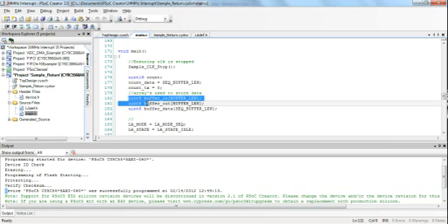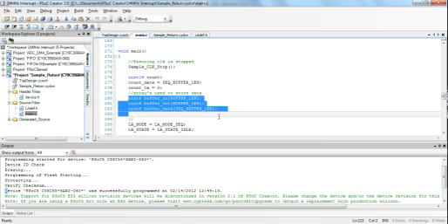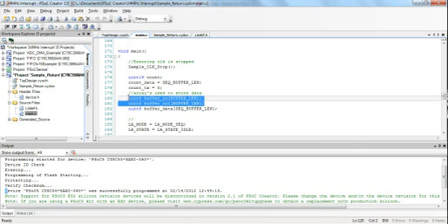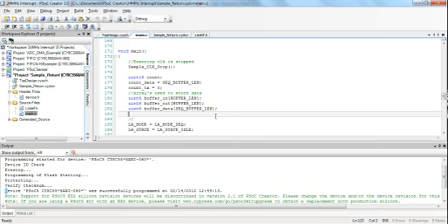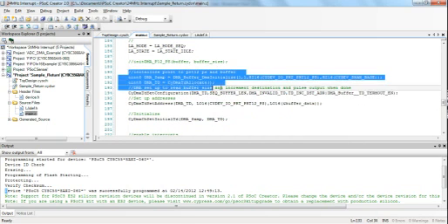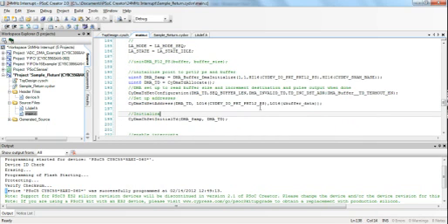You've got buffer in, buffer out, and buffer data. Those are all for the data. Buffer in and buffer out are the USB UART in and out buffers. Buffer data is where the buffer is held by that. This is the setup for the DMA engine. The DMA engine will set itself up to read the port 12 pin state register and send it to the buffer data right here.